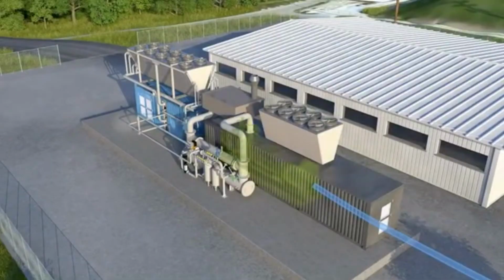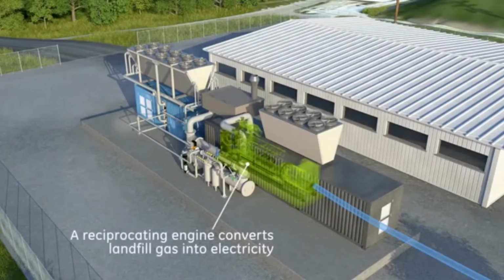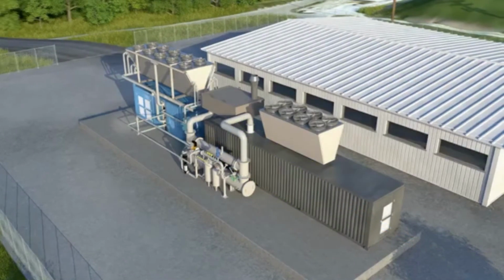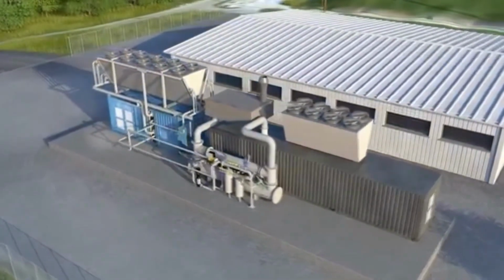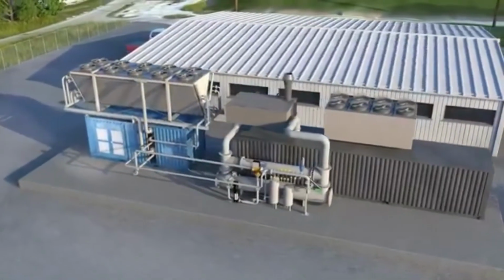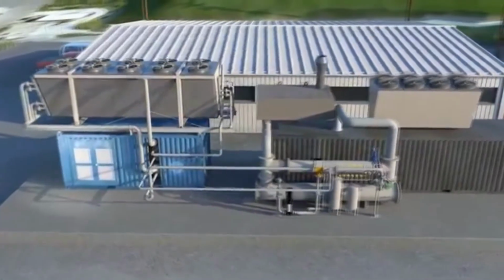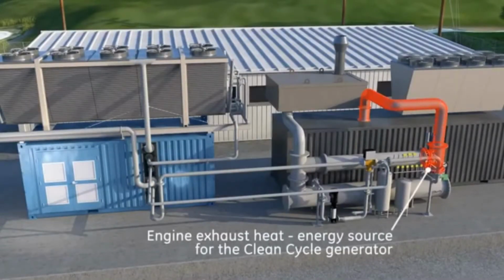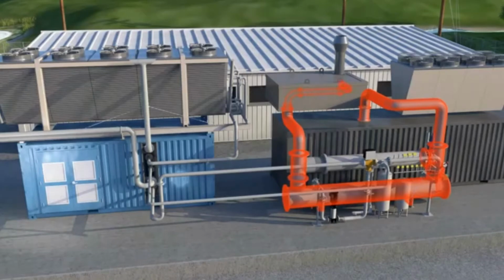The first main component from ORC, organic Rankine cycle, is the evaporator or boiler. The evaporator functions to evaporate organic compound or working fluid into a steam or superheated or saturated vapor. When it becomes steam, with a certain pressure and temperature, it will push the turbine so that it rotates or works. The working fluid, organic compound, completes a cycle as the liquid leaving the pump at stream 4, called the boiler feed filter, is heated to saturation and evaporated in the boiler or evaporator.